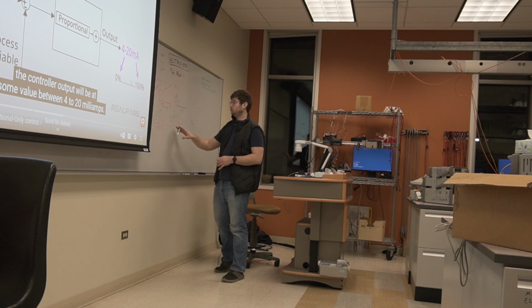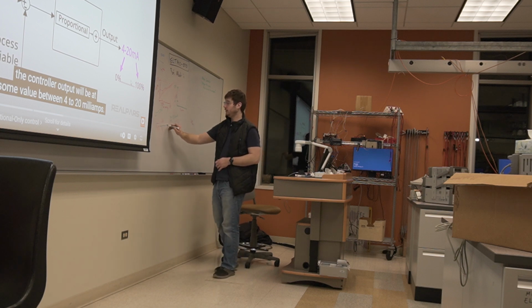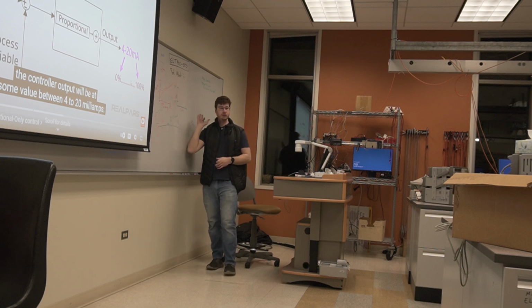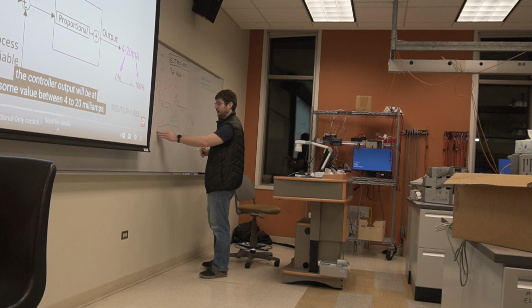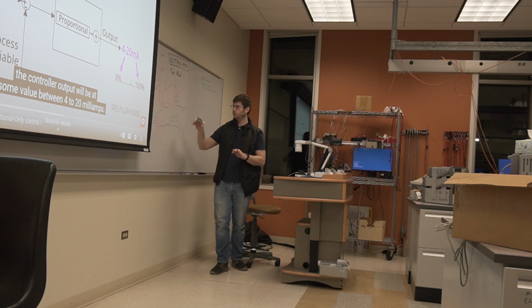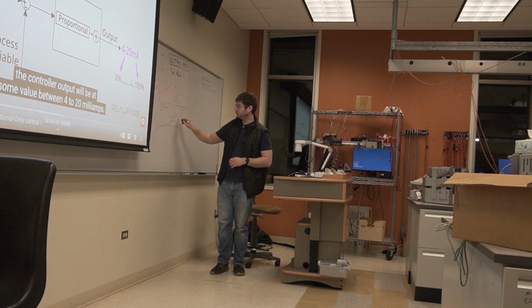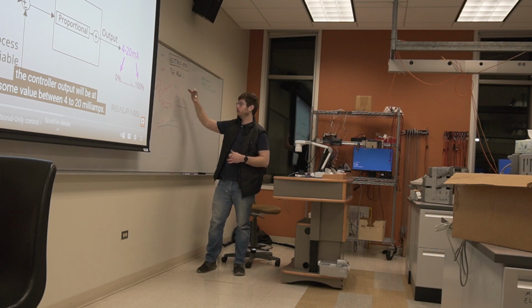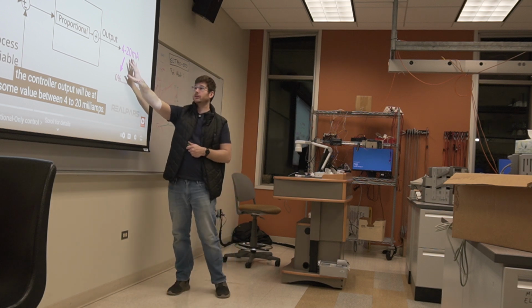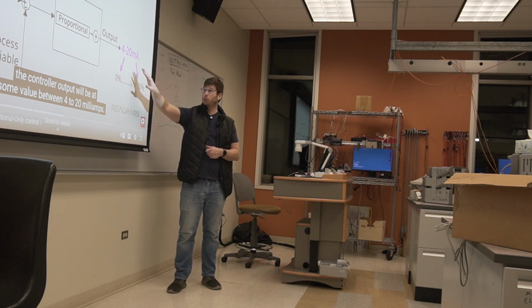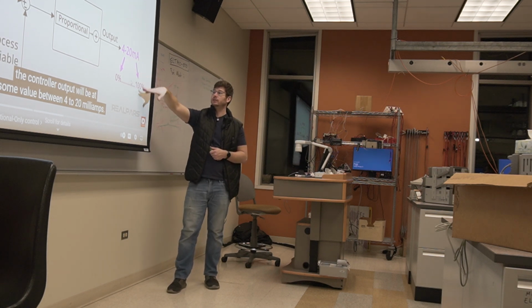I won't get too into why this works, but the main thing is that the amount of current that flows through here, this line could be really, really long, and we can still figure out what we need to send through it to get a given current. They make these things called constant current sources. We can much better transmit information with how much current there is rather than how much voltage there is. So the sensor they're using in this particular example doesn't report in voltage. It reports in current that we're digitizing into our PLC, and that means something.